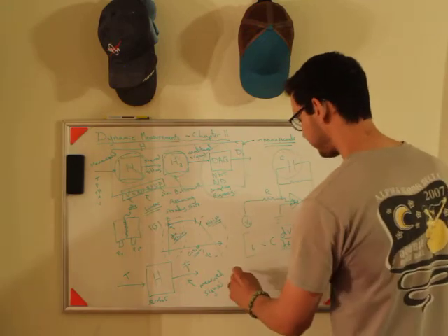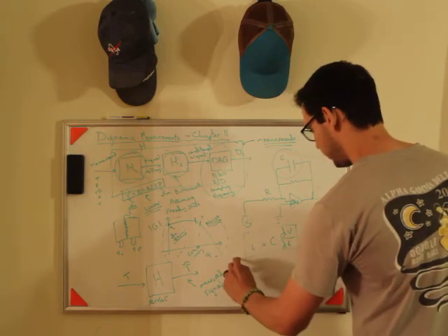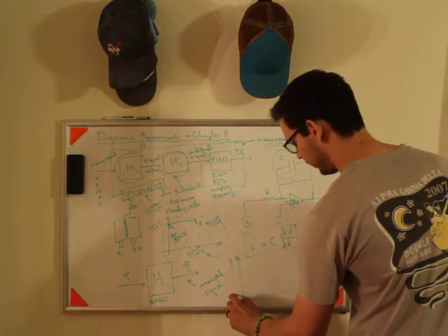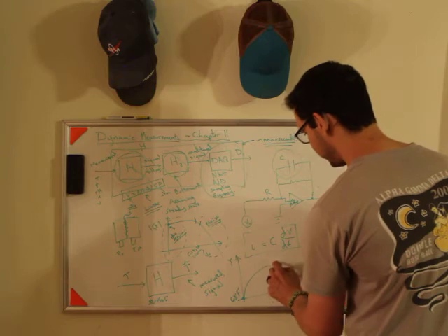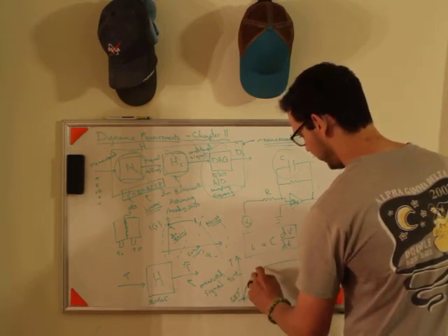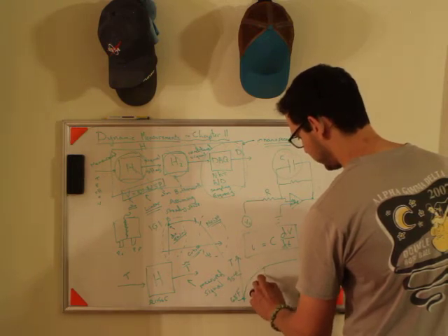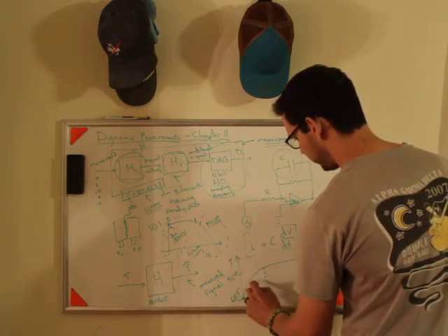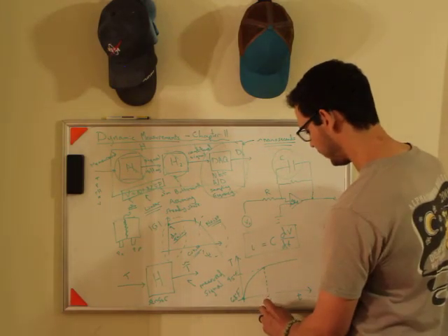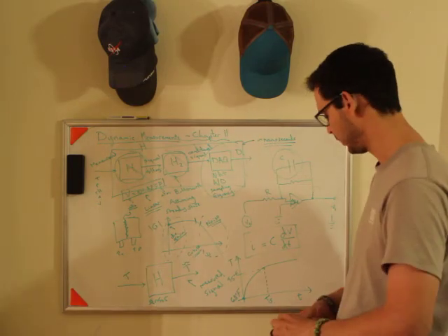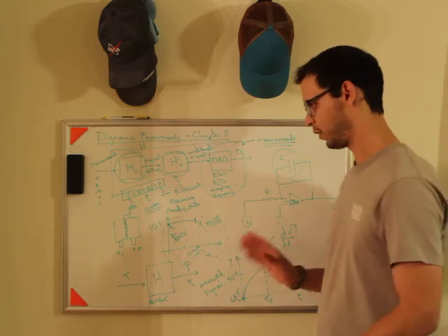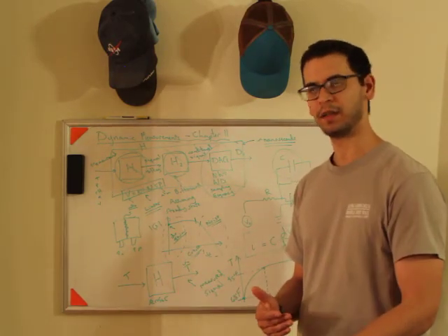And if you plot your temperature as a function of time, your initial condition is going to be 68 degrees, but it's going to slowly ramp up to 95 degrees Fahrenheit. And somewhere in here, you're going to be pretty much within, say, 2%. And this is what we call our settling time, okay? And so what we really care about for a system is how long does it take for the sensor to settle before I can move on, okay?